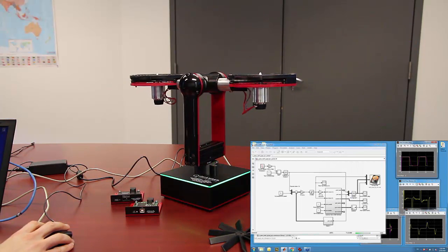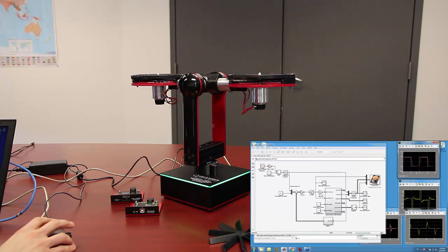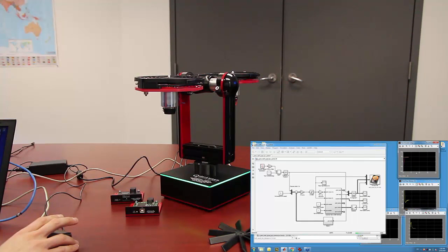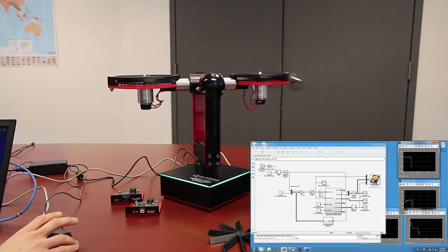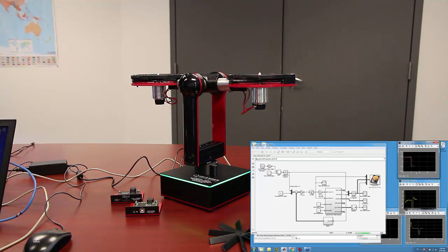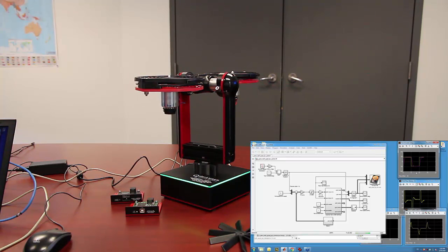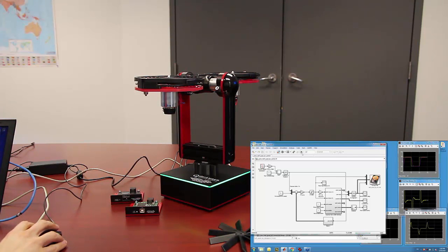Both the pitch and yaw have the same voltage, right? Because of the way the propellers are oriented, you send the same signal. So this is actually using this cross torque effect to move it about the yaw. Now, what's great about this system is it's a great segue for students and researchers alike to study certain phenomena of a full quad rotor, but just focusing on one part of the system.